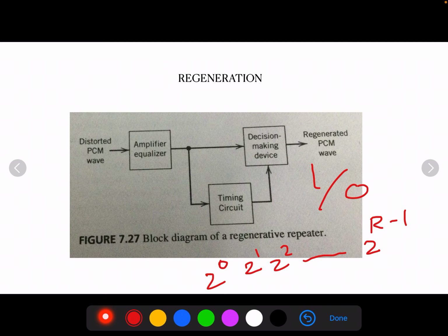However, pulses tend to become more difficult to generate and to transmit as their duration is reduced. If the pulses become too short, impairments in the transmission medium begin to interfere with the proper operation of the system. Accordingly, in practice, it is necessary to restrict the number of independent message sources that can be included within the time division group.